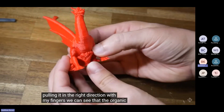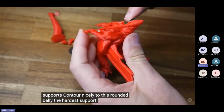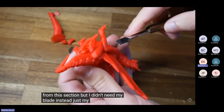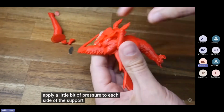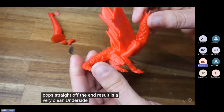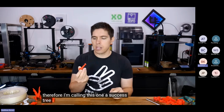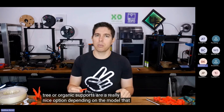We can see that the organic supports contour nicely to this rounded belly. The hardest support to remove came from this section, but I didn't need my blade, instead just my prying tool to apply a little bit of pressure to each side of the support, and then it just pops straight off. The end result is a very clean underside to the model. Therefore, I'm calling this one a success. Tree or organic supports are a really nice option depending on the model that you're printing.